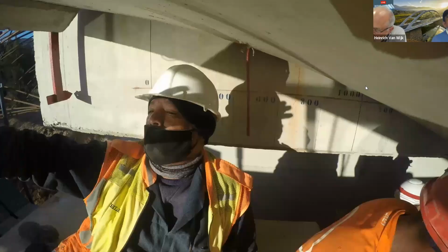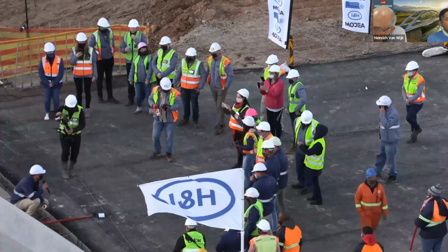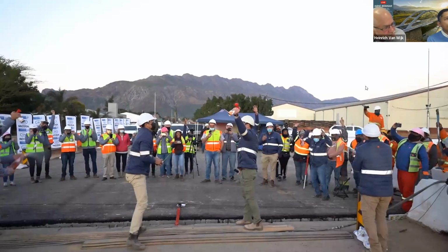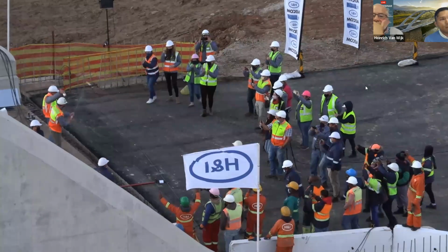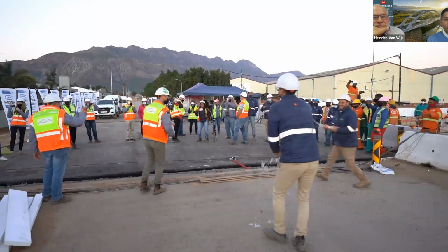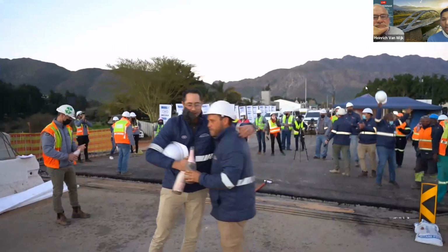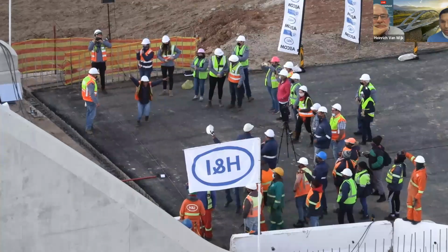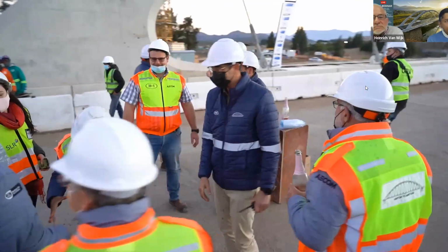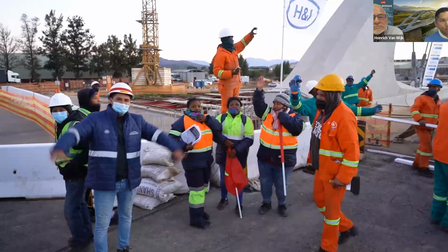I think the nicest way that we could get a real calibration, this is a cable supported structure, so the cable forces are very much dependent on the self weight of the structure. So that's something you have to make sure you get correct. And we had a phase, close towards the end of the structure, when we were installing the permanent bearings, where we were able to jack up the structure and install them. When you jack up the structure, you're able to get to the real weight of the structure.